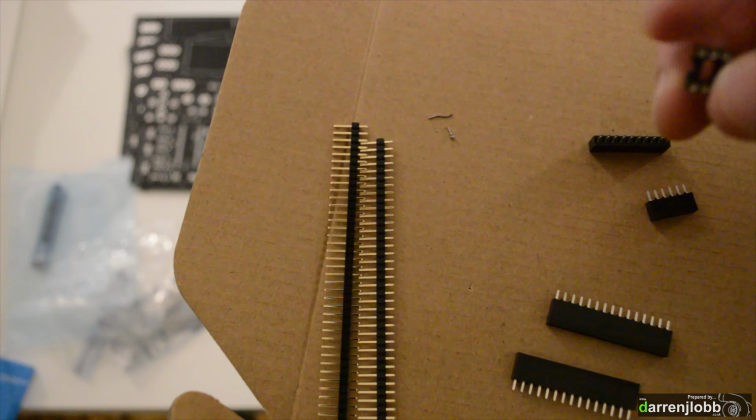Rule of thumb for pretty much all the components is you want to make sure they're sat right down flat on the board before you solder them. If they're up proud from the board, they can move around, and when they move around they'll break, particularly the connections. It's worth visually looking at all your connections after, to make sure you definitely got a good connection down to the board, and also that you haven't accidentally bridged anything, which we haven't.